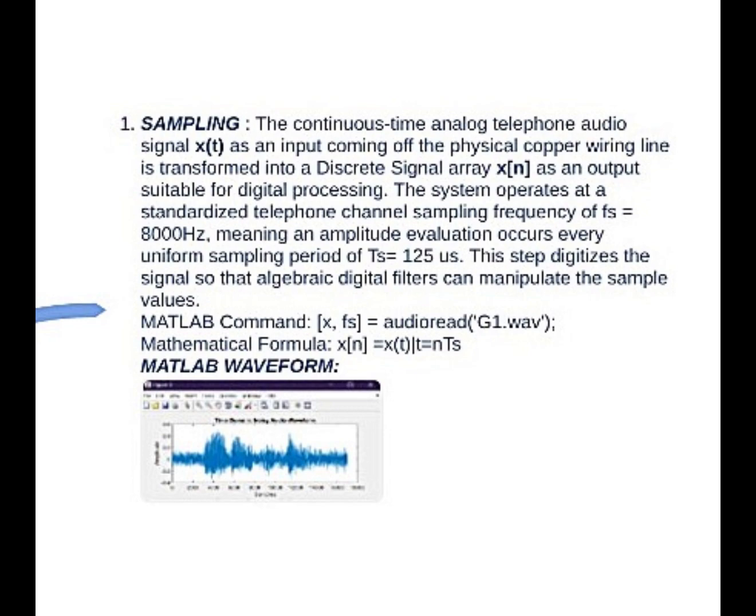This discretization process populates our digital data array in MATLAB, translating the analog acoustics into accessible numerical values. The resulting discrete time waveform plot reveals structured speech envelopes clustered within distinct sampling regions. However, a continuous wideband baseline fluctuation persists across the entire sampling duration, indicating heavy deterministic noise corruption. Looking at raw time samples alone cannot isolate the specific noise frequencies, dictating a transformation into the frequency domain for spectral diagnosis.